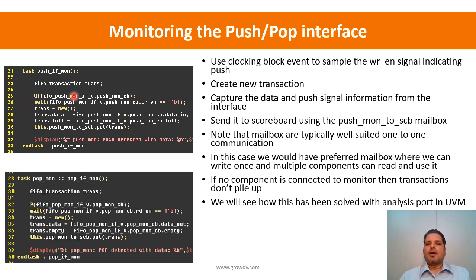Because in the push interface, we would like the data to go out and the full information to come in to the test bench, and then we want the write enable to go as an output from the test bench, right? That direction would be reversed if the same port was implemented in the DUT. But for the monitor, we want all the signals to be input.